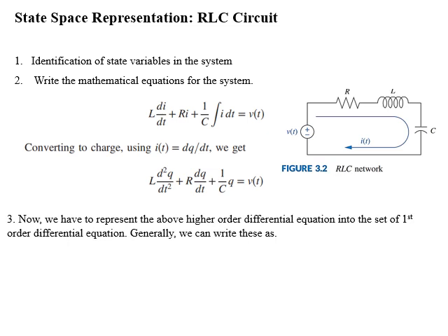Now with the help of example, we will study how to form a state space representation for any system. In the given example, we have to make a state space model for an RLC network. Dear students, first step in analysis of any system is to find out ordinary differential equation defining dynamics of that system. For this RLC network, first of all we will write KVL equation, which is first equation of this slide.